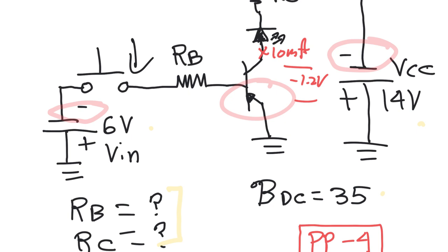Okay, so take that down. The beta, we're going for a lower beta because we're getting down near the saturation region, so we expect the beta DC to drop. Right, I didn't give you the LED voltage here. I want that to be 2 volts. Go ahead with your circuit in front of you and solve it.